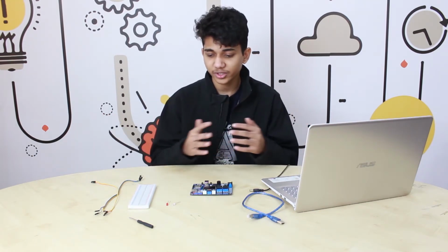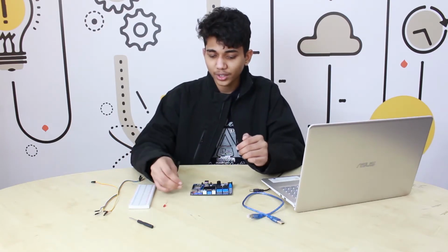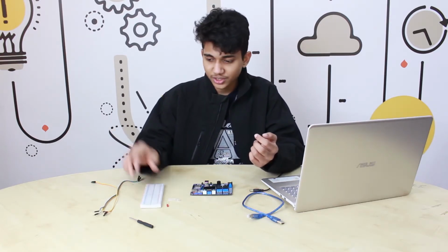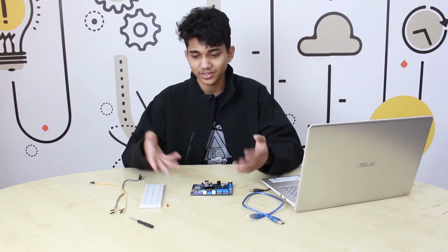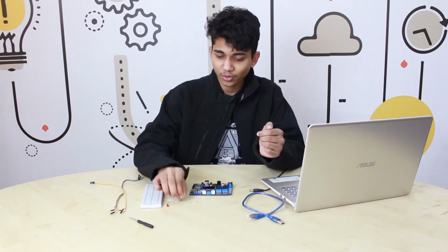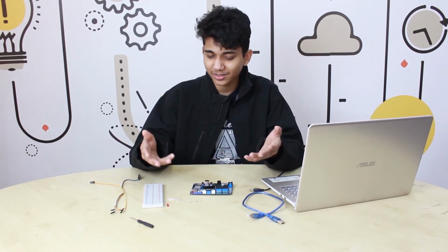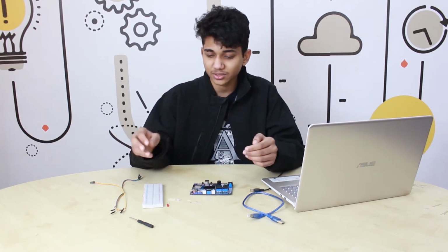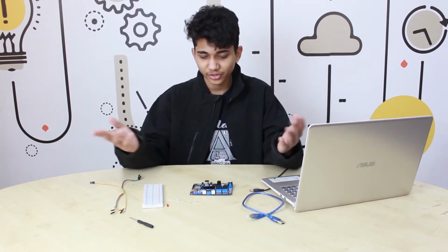So why are we using these components? Well, we're obviously going to use the LEDs to turn on and off to demonstrate our project. We're going to use this breadboard for connections, jumper wires too, and the main protagonist of this whole series, the School of IoT Development Board. And along with that, you can see that there are resistors. So where are we using resistors? Well, you see, the School of IoT board gives out a lot of current, so we are going to reduce it so that our LED doesn't burn out for long-term use. Aside from that, we're good to go.